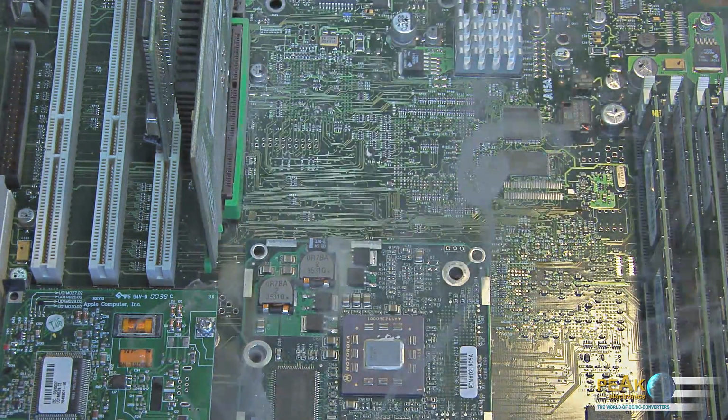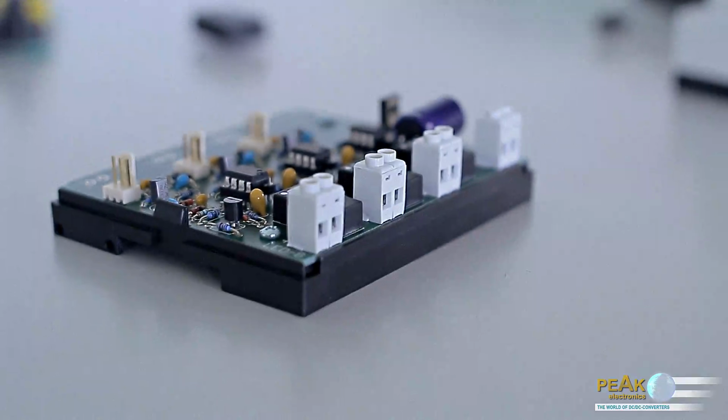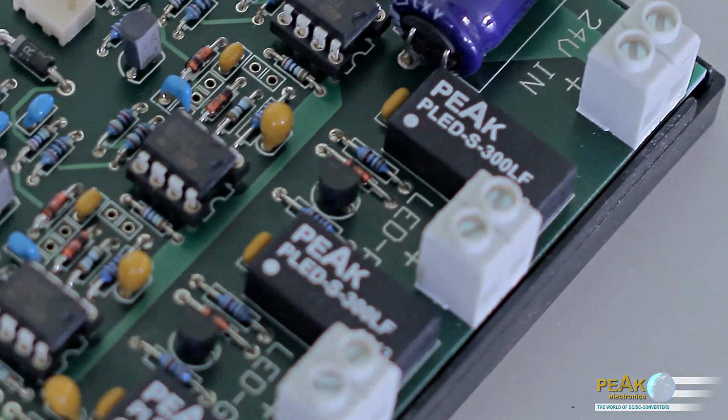Instead of a melting fuse, a resettable fuse, such as a PTC fuse, can be installed. A fuse should always be built in when the applied voltage source to the converter has a very high power in order to supply many loads at the same time.